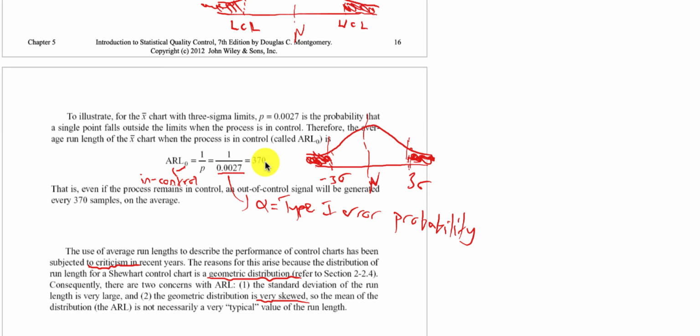Because of the randomness, and we assume that this randomness is in normal distribution, we have a probability that we are going to observe some out of control points after some samples, and actually they are not the things resulting from assignable causes.